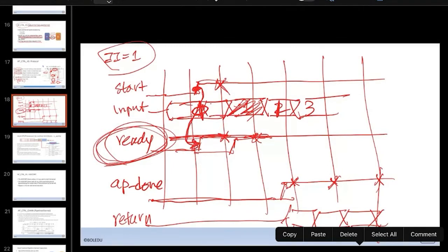This is a very bad design principle. Yeah, the timing will be too critical. Yeah, so normally the kernel function doesn't see start until you sample it at this clock edge. Yeah, if you see the start here and then you assert the ready here, then the best II you can do is 2. Okay. So you must have a ready asserted before you see the start.